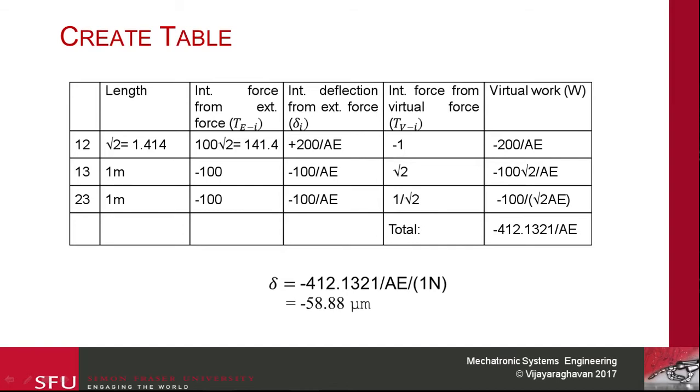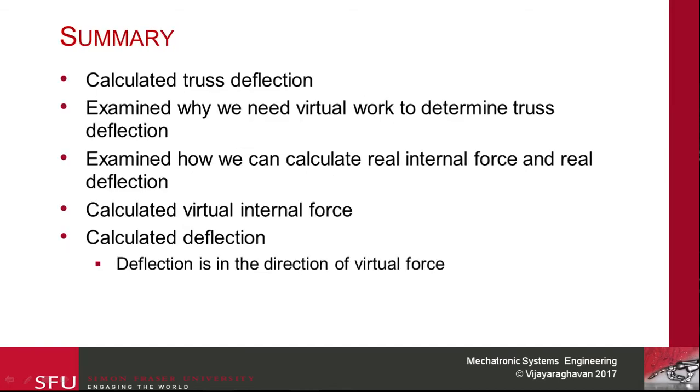In summary, we calculated the truss deflection using a regular method, and then we examined why we needed virtual work, and how we can calculate real internal forces and real internal deflections, calculate the virtual internal force, and then calculate the deflection using the method of virtual work. This method can be extended to calculating the deformation along any direction. So this concludes our video. Thank you.